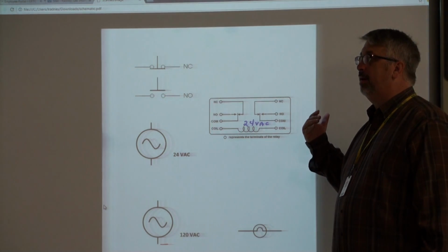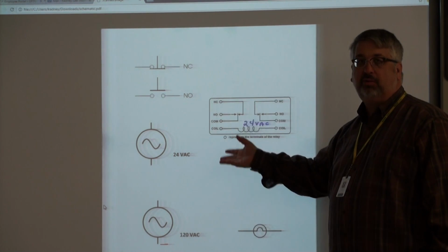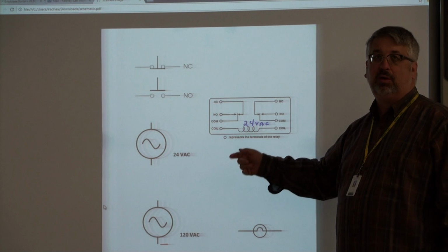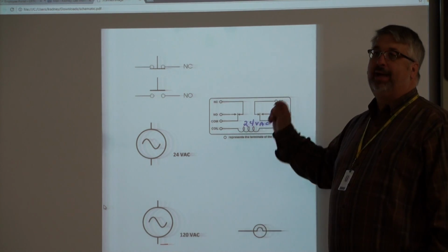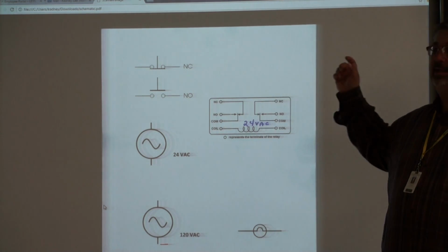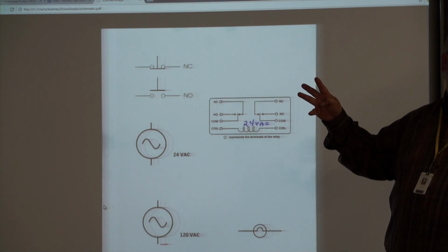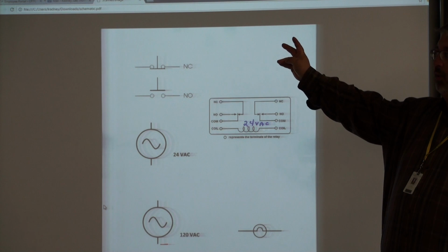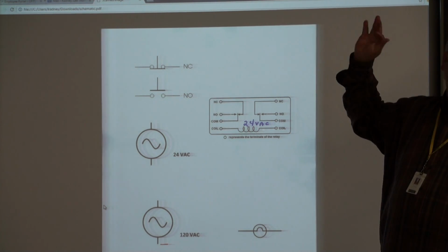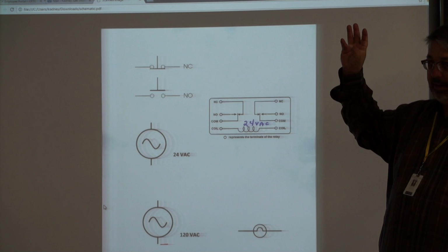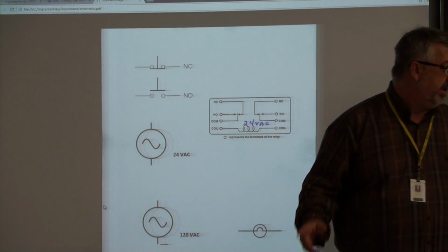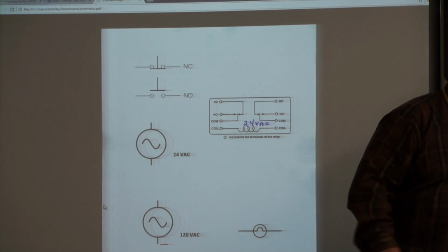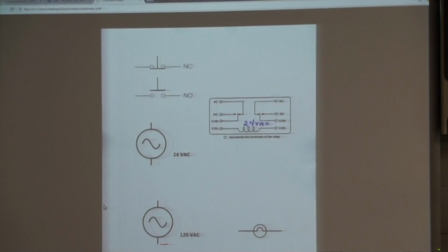Build the circuit first that controls the relay coil. Build the circuit that turns on the light, and then build the circuit that latches that light on. So you really have three circuits: one that engages the coil, one that turns on the light, one that latches the light. If you take it circuit by circuit by circuit, I think you'll get it. So we'll run down the hall just a minute, and I'll be back. Then we'll do it collectively.